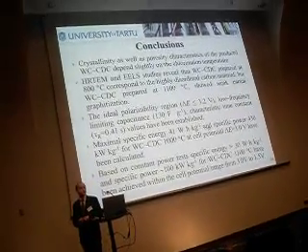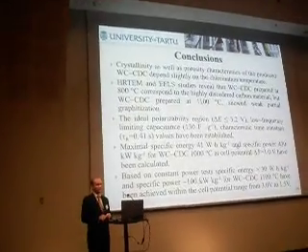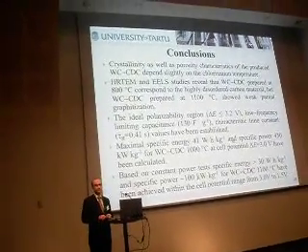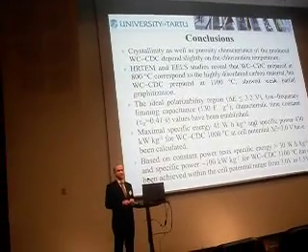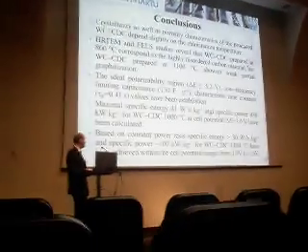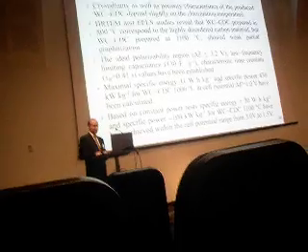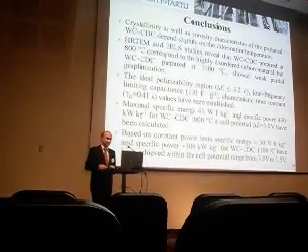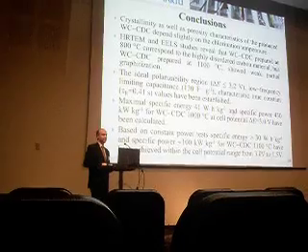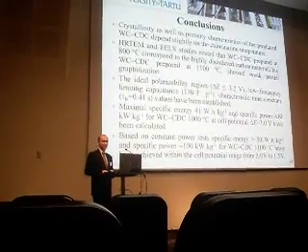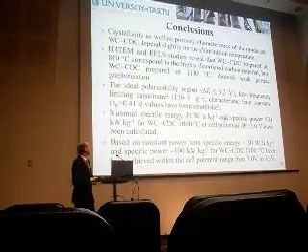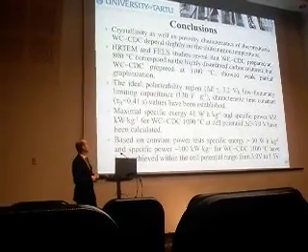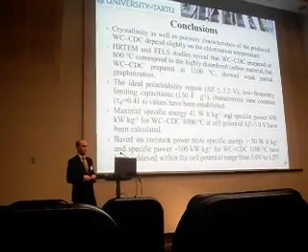And as a conclusion, the crystallinity as well as porosity depend only slightly on the chlorination temperature, and also the high resolution transmission electron microscopy and X-ray show that there is only weak graphitization, and that's in the material that was synthesized at 1100 degrees.